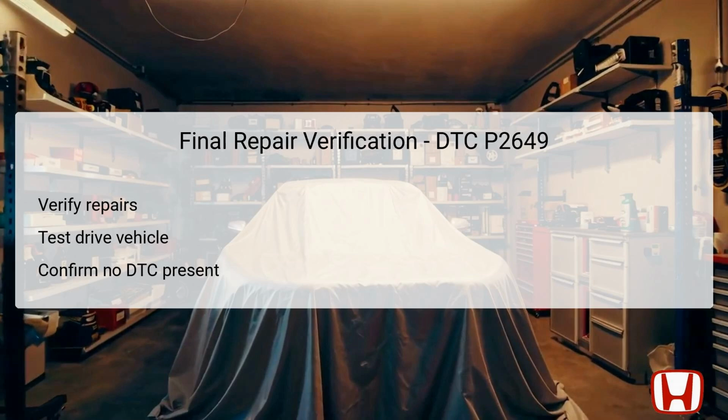Following this, conduct a test drive to observe the vehicle under various conditions, assessing engine performance, response, and any related symptoms. After the drive, utilize the Auto Diagnostics system HDS again to confirm that the DTC has not returned and that no new codes are indicated. Successful resolution is indicated by the absence of the DTC and satisfactory vehicle operation.